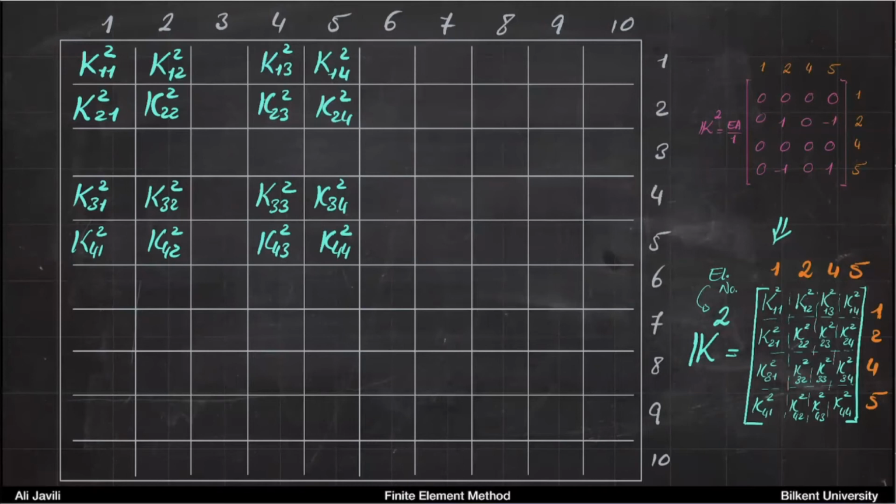But now, if you also look at it, we see the same story. The main diagonal components are always positive. Again, let's say assume it positive, or at least it's not negative. And as you can see, the main diagonal ones come here also on the main diagonal of the bigger system. And also, if you pay attention, this is symmetric. So K12 and K21 are here. And then on the 4, 4 component of the big matrix, this would be, let's say, 4th row, column 1, and this is 1st row, column 4. If you look at the 4, you see this, and then if you look at the same thing for the 5th, you see the same symmetry basically holds. So the big system is also always symmetric.